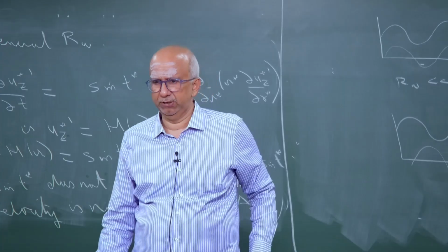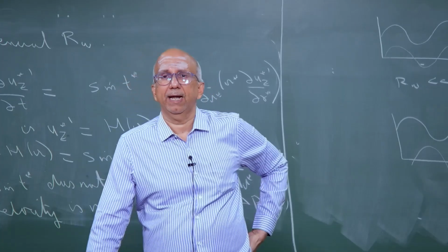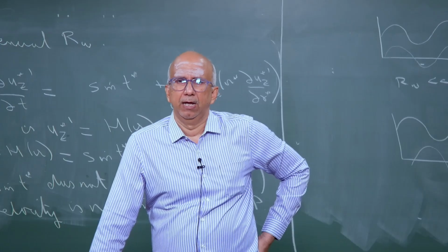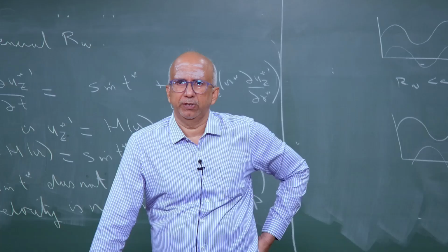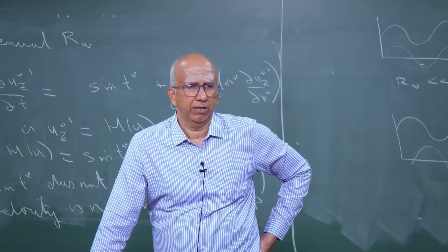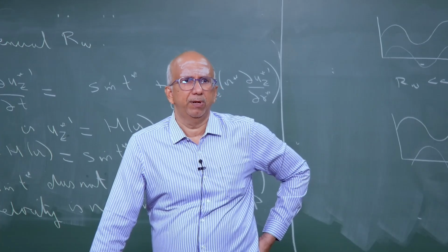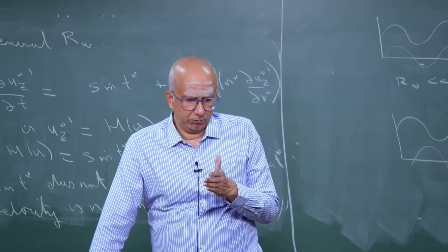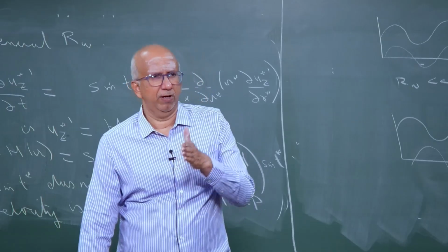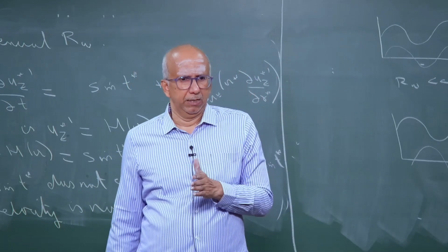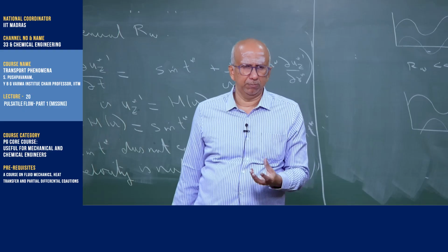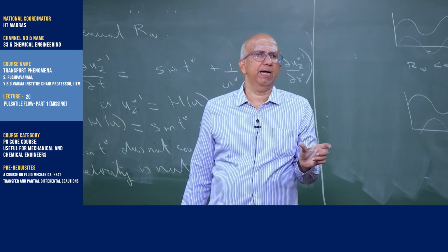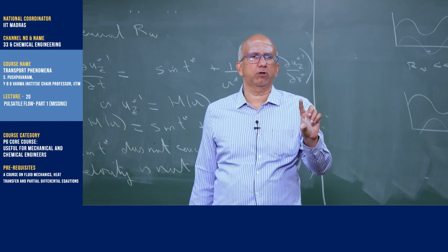That is what I mean by in phase, and that is only in the case of low frequency, when omega is very low, when RW is very low, the Strouhal number is very low, the way I have defined it. Momentum diffusion is very fast. Okay. So as soon as delta p changes periodically from one value to the other value, it is changing so slowly, my momentum diffuses so fast that the liquid quickly adjusts to this different pressure drop.